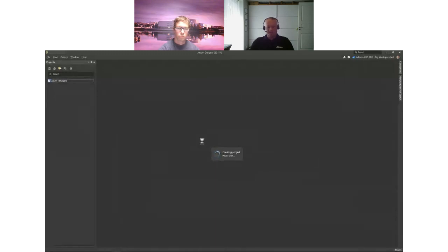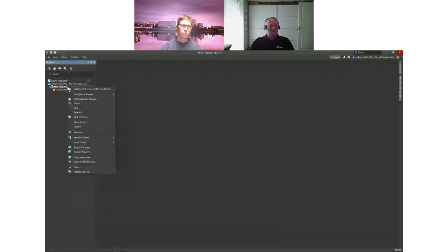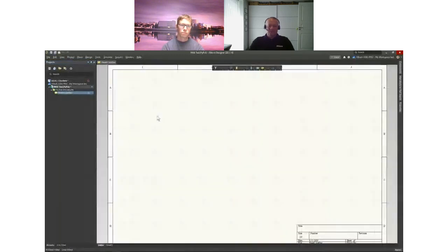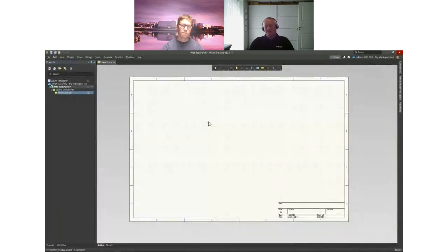Now I see that it's taking a little bit longer time than normally. I think this is because I am also using this webinar stuff here on my internet connection. But now the project has been created, and the first thing I would like to do here is to add a schematic. So I'll right click and say add new to project, and I will add a schematic. It will generate the schematic here, and in this case, I won't do any fancy stuff like adding templates from the managed template of my workspace, but just simply keep this one here.